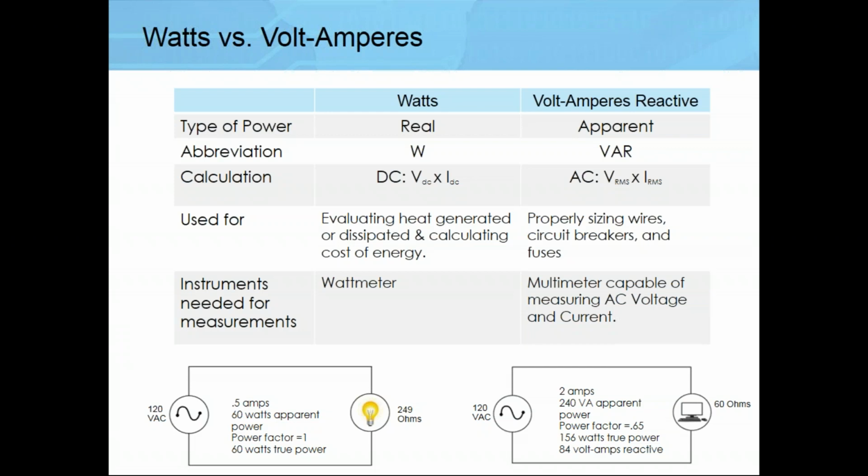The total power required is a combination of the watts that are required and the apparent power that is required, in terms of VA. So if you ever see power requirements that are listed in VA, you know that this component has some kind of resistive element, some kind of capacitive or inductive element, which will allow it to have a rating for voltage times ampere. If you have just a purely resistive load, you're going to see watts listed on it.